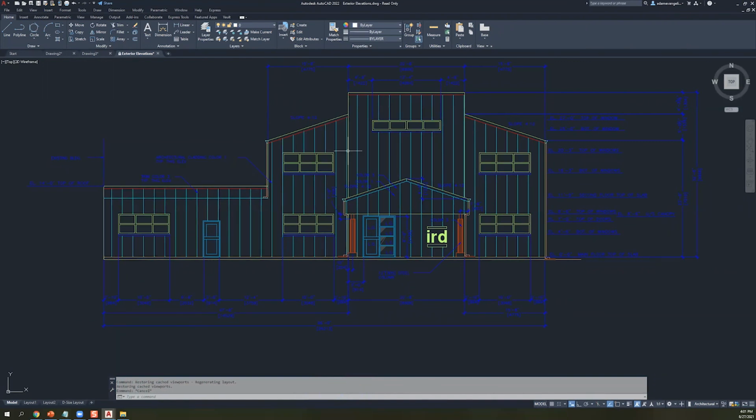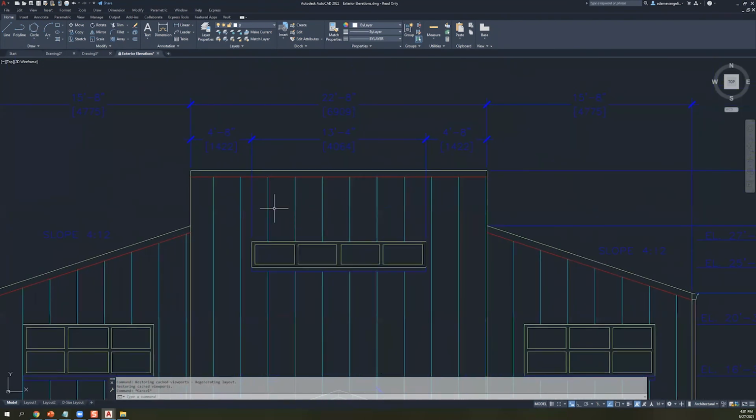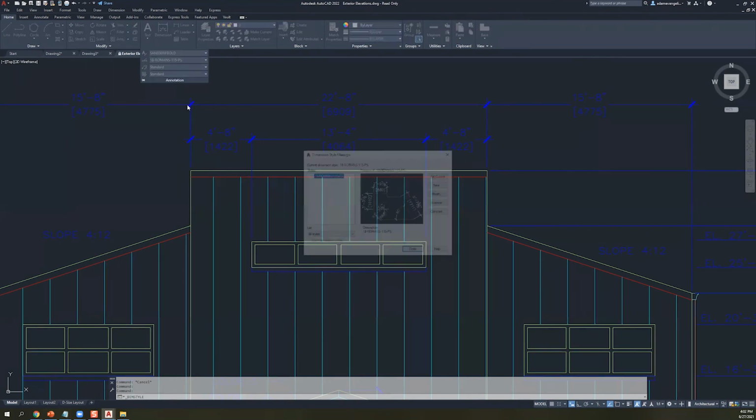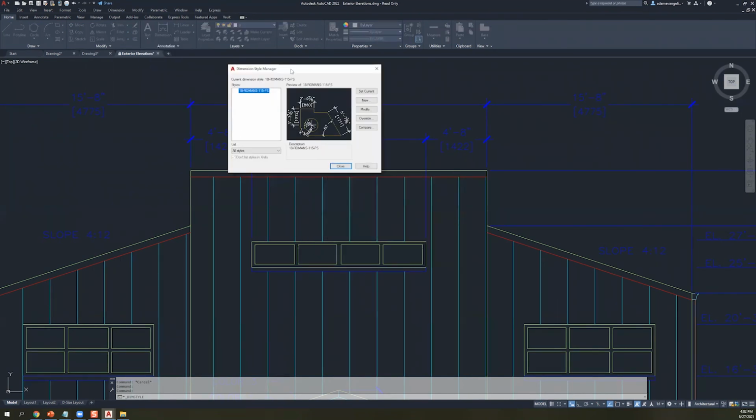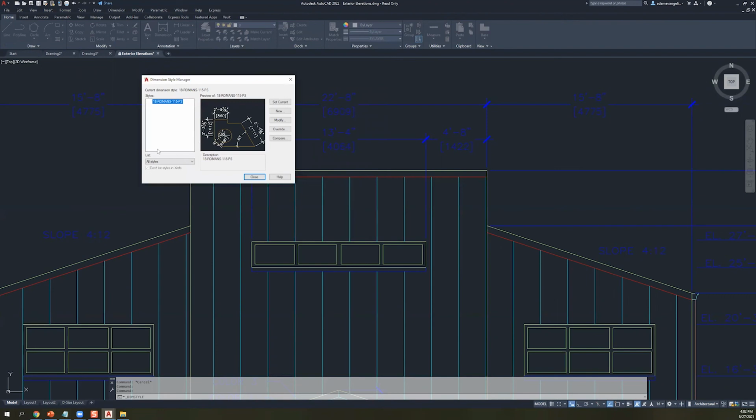right? Like I said, this building is one-to-one technically, right? That means that this lettering and this font has to be at a similar scale, where this 2 is like 1 foot tall or something like that. It's pretty big. That said, where does that information come from? We could take a look over at annotations, and let's say dimension styles, for example. Dimension styles will determine the scaling and the relevance of all the stuff that you're trying to do over here, right?